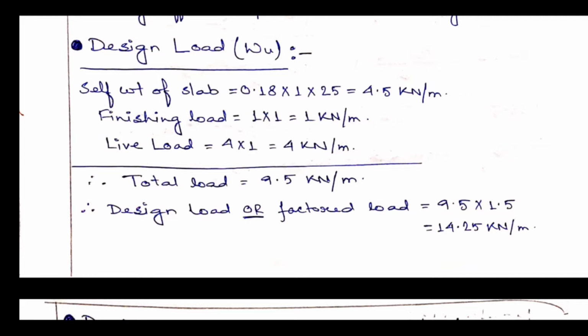Floor finish load is given 1 kilonewton per meter square in question. So 1 into 1, that is equals to 1 kilonewton per meter.